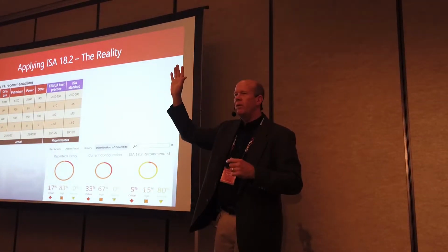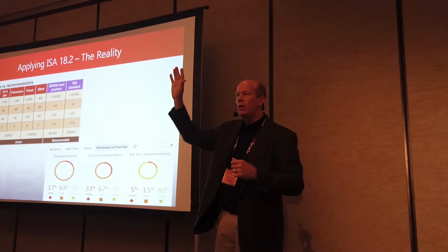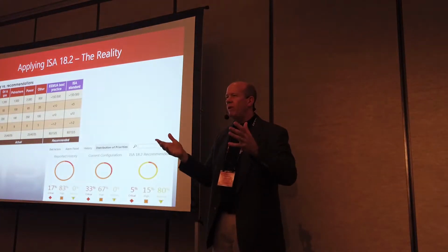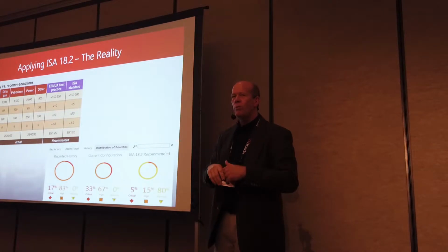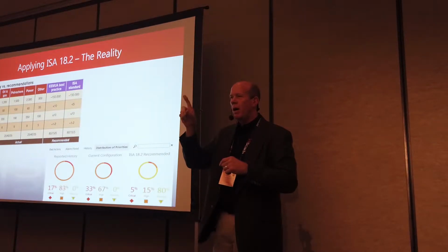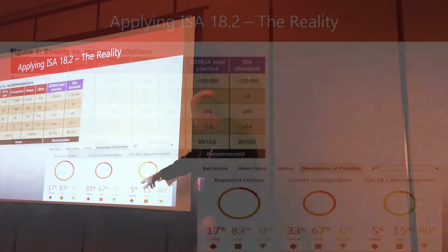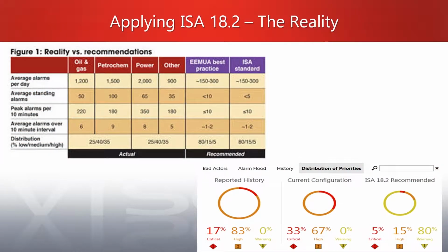Now, who went to the alarm notification class before that Greg gave? Good class. So help us out here. When he was showing it within VTScada, what class of alarms or options is a checkbox for dial out? 1 or 2. This would be a 1, the critical is a 1, and high is a 2, okay? In that terminology. And by the way, that makes a lot more sense here in just a moment on the 1 and 2. Let's go to the next page.